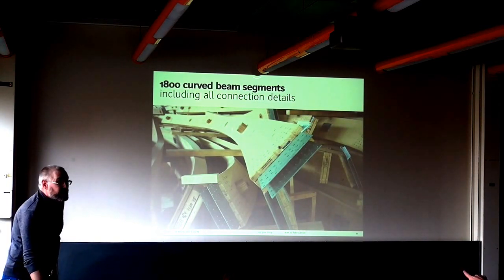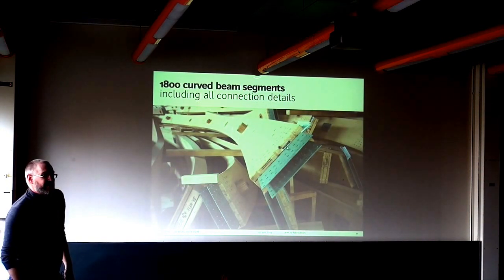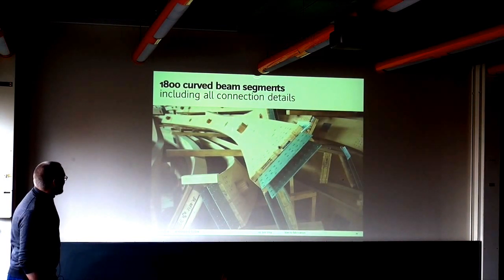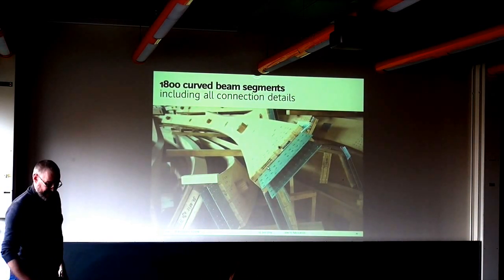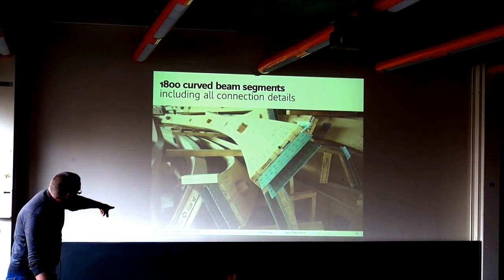So black marks a numbering system? This is not a numbering system yet, but the number is actually on the other side. This is marking which end that is. There's either two lines here or just one line, which tells you whether it is the front or the end of the beam. Down here you can see the number if you look closely, there in the corner.